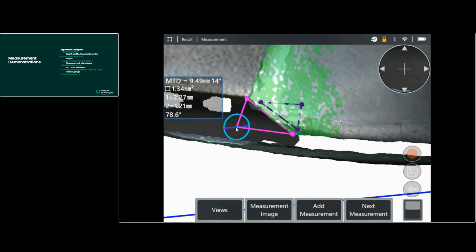Obviously, that's missing material here. So where do we place that cursor? So make good use of the 3D surface masks so that we've got good agreement between this surface and this angle of this missing material with the intact material on the edge of the aerofoil, and same along here along the tip of the aerofoil. So we've got good agreement of the 3D surface mask projecting along the plane. And yeah, so we're getting good agreement. I've done this a couple of times in rehearsal, so we're getting good agreement of 1.5 square millimeters.